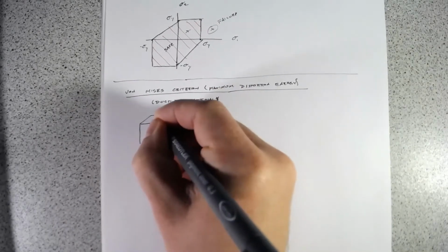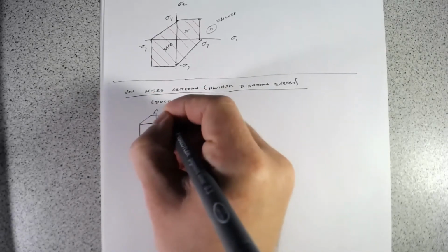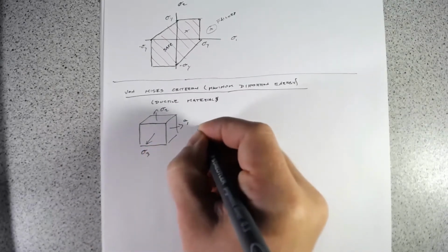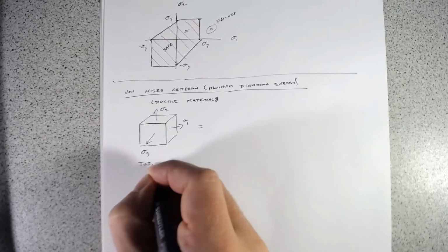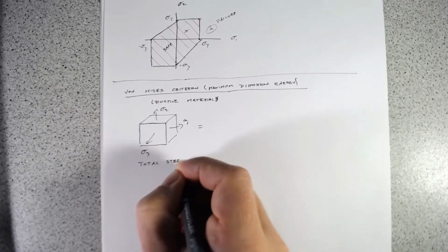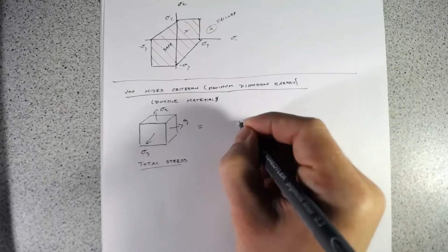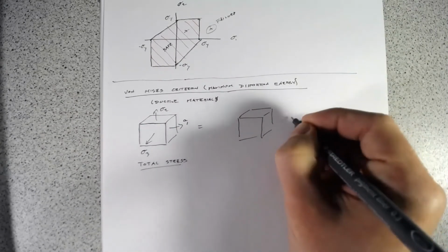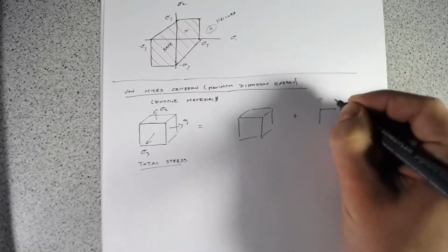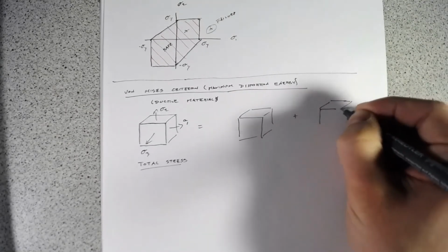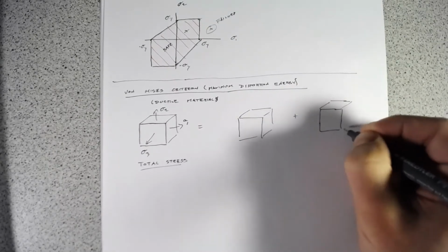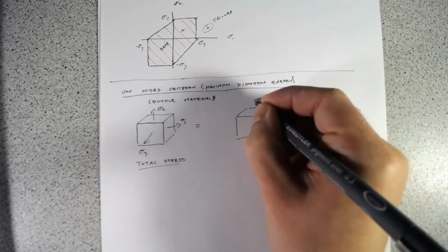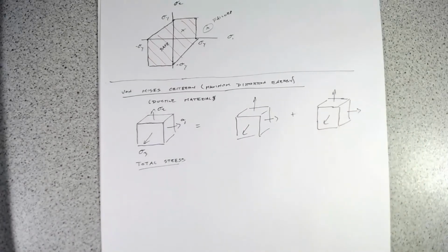So if we look just at principal stresses, sigma 2, sigma 1, sigma 3, so that's our total stress state. Well, it says that that's actually a combination of the average stress plus, and then if you subtract out the distortion energy. And by distortion, think of this as, again, kind of like shearing.